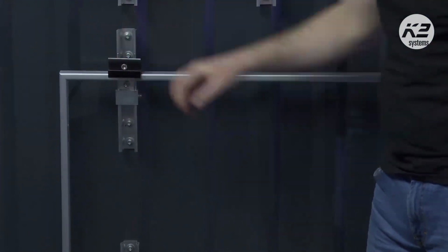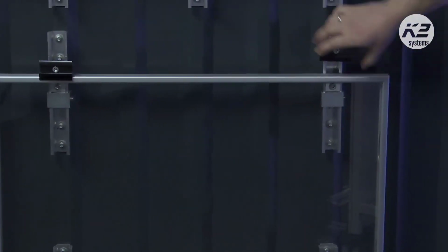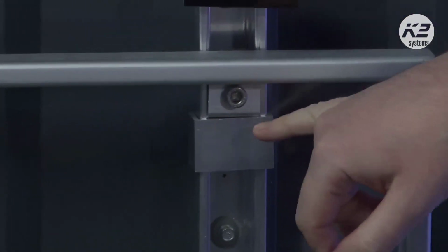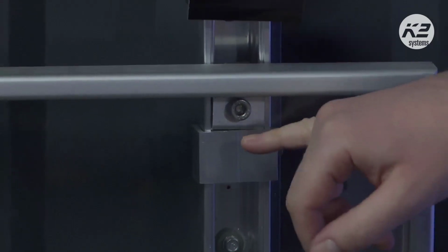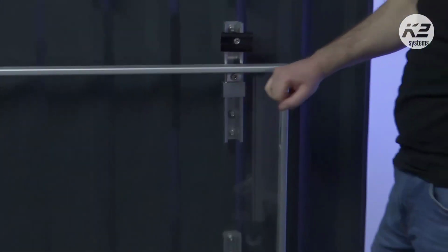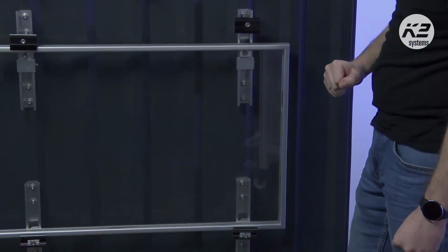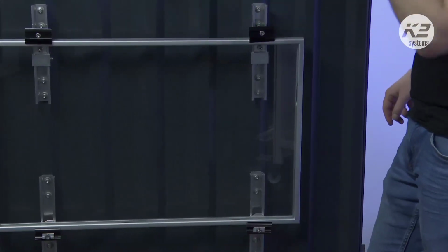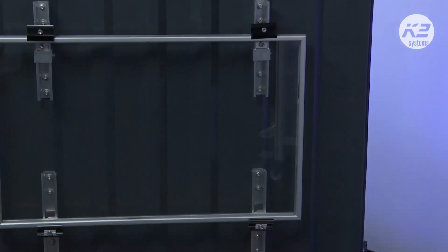And just tighten it in. So for the fastening, this anti-slip clip you have in every second row from the bottom of the module field. So I believe that's it about the simplest system with multi-rail with facade clamps.